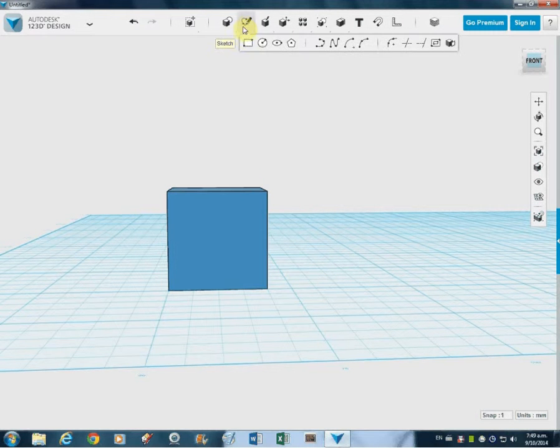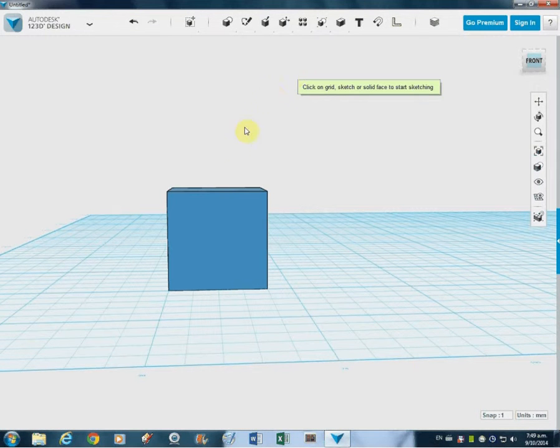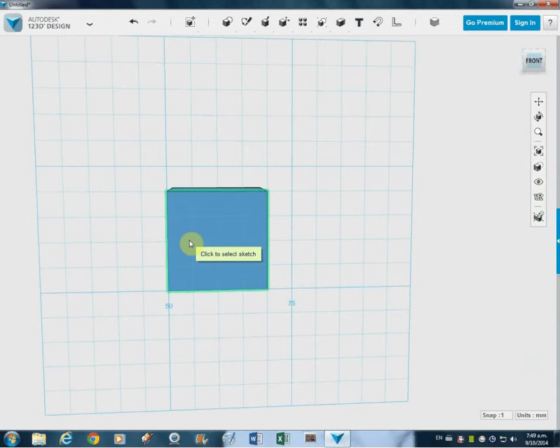to do that I go up to the sketch tools and I'll start with just a standard polyline. The first thing that I have to do is specify what I'm going to put the sketch on, so I click on the face of the box, there it is. Then I have to specify where I want to start, so I specify there. So it's kind of a process, it's a bit weird but it's all process.